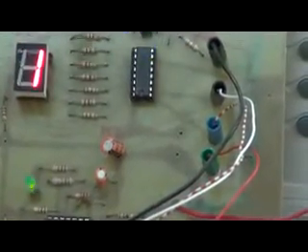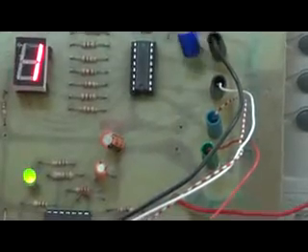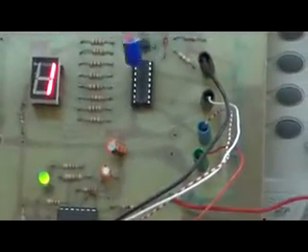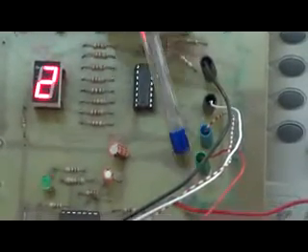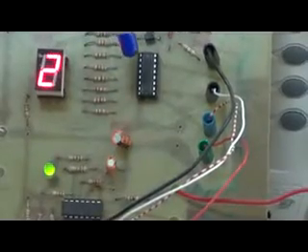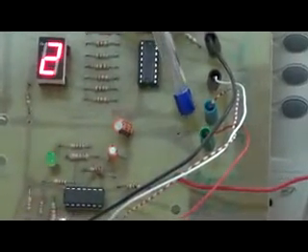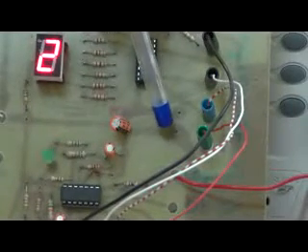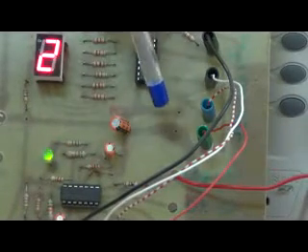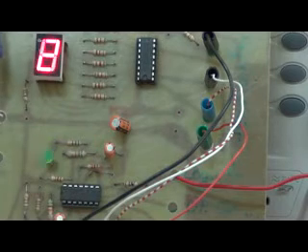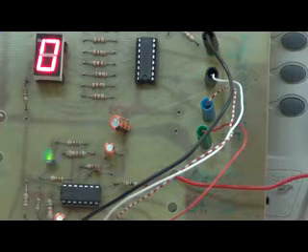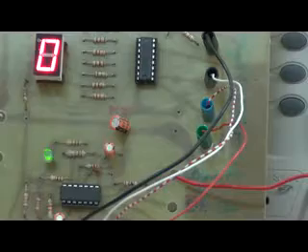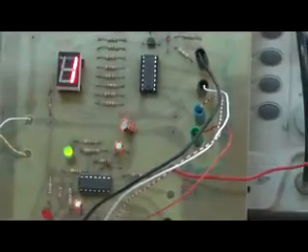Since we need only 2 bits for this counter, we have grounded the MSB and the second most MSB of this hexadecimal input, and the rest two we have connected with the output of the counter. So depending on the output generated by the counter, the output is observed on this 7-segment display. Depending on the output generated, like 00, 01, 10, we are getting the output, and it is displayed on this 7-segment display in decimal form.